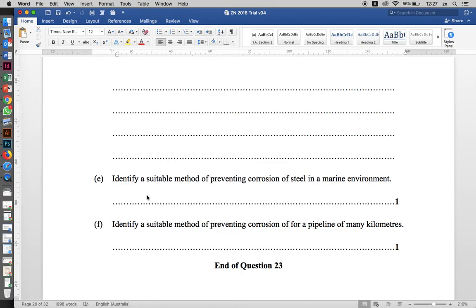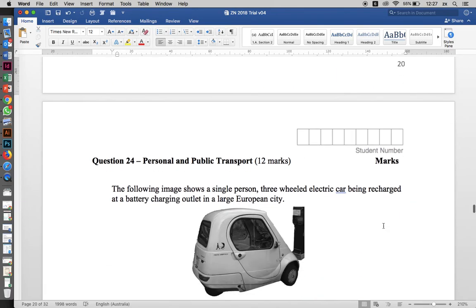That's the answer I'm looking for there. Some people use alternate materials, and that's not a bad answer, except that there's not really a suitable alternative. People talked about concrete. The problem is that the concrete still has steel in it, and that concrete gets cracks. You have a problem. The second option, someone said PVC, and the PVC is just not strong enough for a multi-kilometre pipeline.